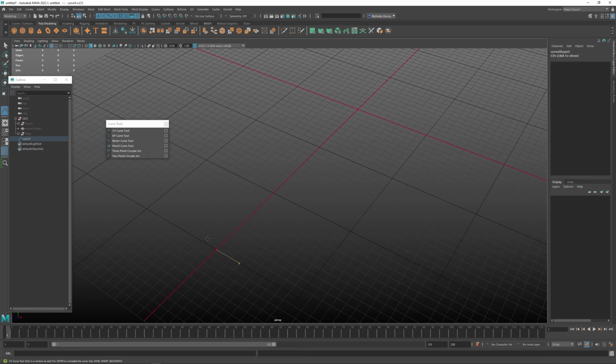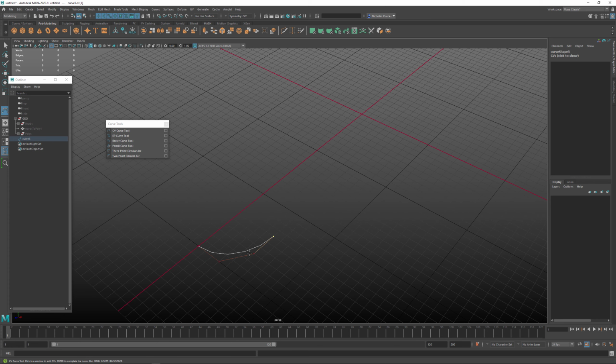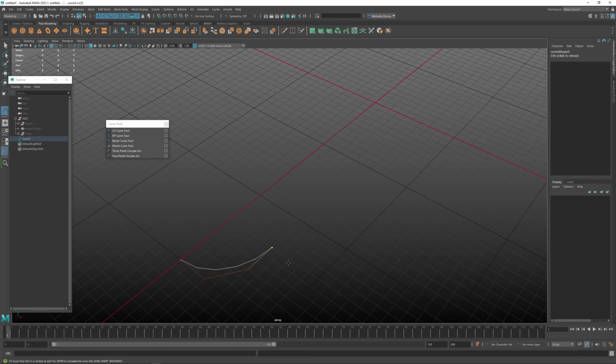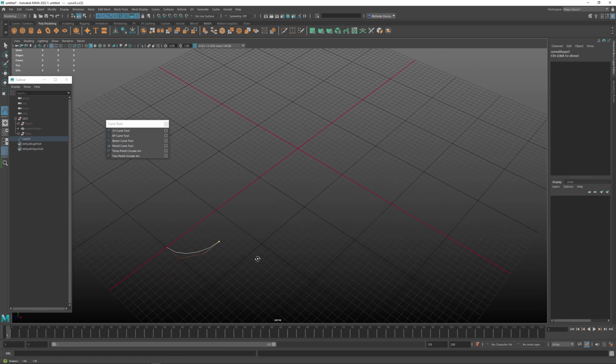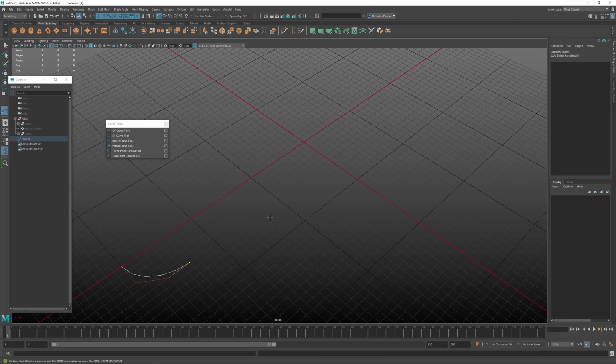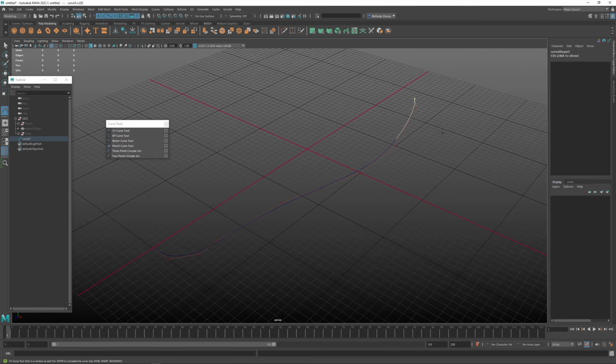And the weird thing about this tool that I think is kind of odd is you don't actually start drawing a curve until you hit point, point, and if you hold down X and draw another point, we need 1, 2, 3, 4 points to start actually drawing what the curve is on here. And you can see that these points, these control vertices, are approximations to move this actual curve here. So I know that probably feels a little bit odd at the very beginning, but I'm just going to hold down X, and I'm going to continue to try to snap to the grid like this. And I think that looks interesting enough. I'll go ahead and hit enter for that.